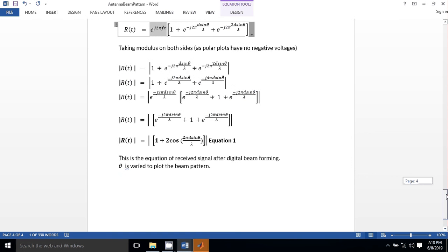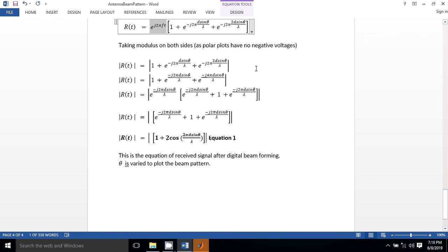So we have 3 antennas here. So we will take d equal to lambda by 3, and further we can simplify this equation. Here we have taken some element as common to form an equation, and finally we get this equation. So finally, we'll use d as lambda by 3. In the case of a 2 element antenna, we use d as lambda by 2. Here we'll be using d equal to lambda by 3 to avoid the side lobes.